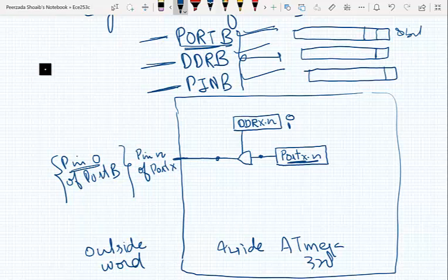This is how we configure a port, by writing something to the data direction register. We may write 0 and this port won't work as output port, and if we write 1 to our data direction register, since this data direction register controls the buffer between the port X register and the outside pin, this port can be used as output port. Similarly, the incoming data, as I have told you, gets stored in the pin register, in case of pin N of port X, maybe PINX.N.